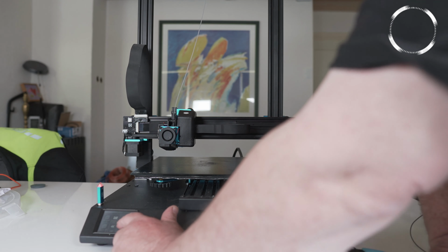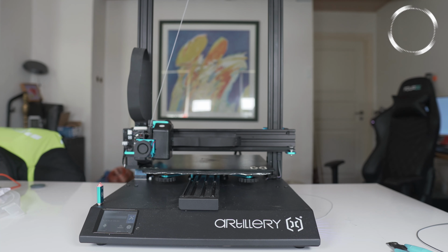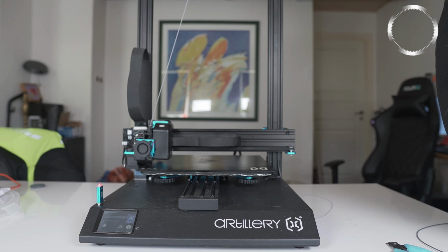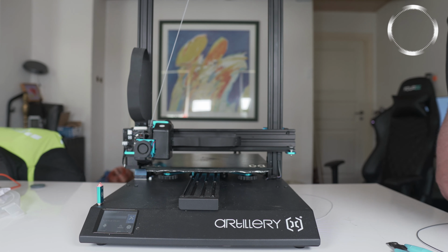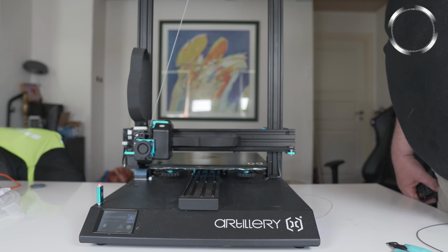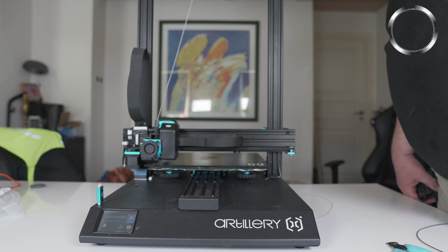Just a comment. The start code is making a G28 that homes all axes, and then lifts the nozzle, so it is easier to clean the nozzle of filament while it is heating the bed and nozzle. So the bed is 62 and the nozzle is 229. We will now prime the nozzle, and I see there's filament coming. I always follow the first layer, and so far it looks good. So let's see what's going on out here.